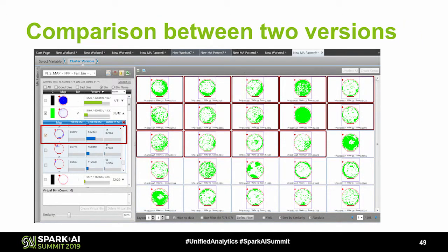So firstly, in the original MA, which employs batch, when we click the clustering result, we can see the 14 wafers which construct the clustering result. Another disadvantage of the MA batch is that it cannot adjust the parameter C, which is the cutoff value for the dendrogram. Since batch processing includes multiple clustering and merging procedures, it is very hard to change the cutoff value C for the parameter. Therefore, it has a limitation on detecting more specific and accurate clustering patterns.